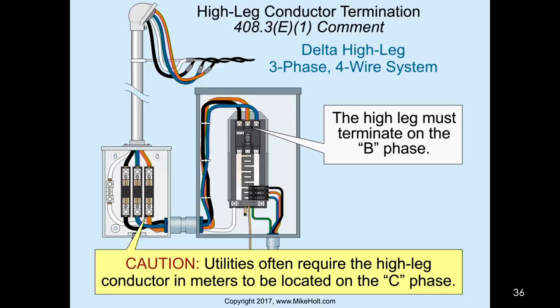Brian. Just one other thing while we're talking about 120, 240, and I think Eric briefly tried to cover it. If you run into one of these, you have to be very, very careful on a high leg delta transformer that you don't have a huge number of 120 volt loads. They typically, and it fluctuates between the transformers, but the older ones were about a 5% loading on any single leg of 120 volt line to neutral loads.